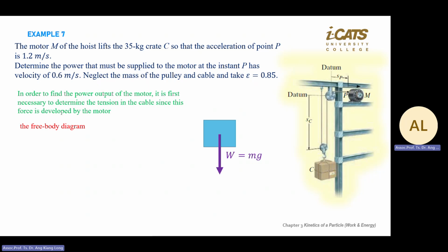Then you solve for internal force, friction, drag, and all this. So for the parcel C or the weight C, you have two tensions, 2T pulling the thing. You can put T, but later you need to use half T, so we just simplify the equation. And our datum is going down positive, based on the datum.